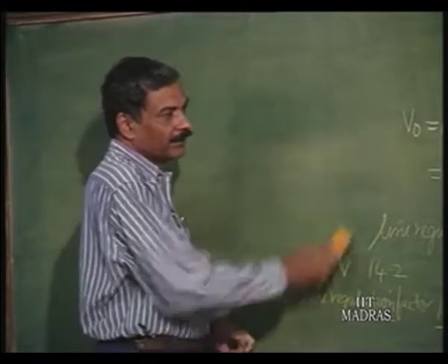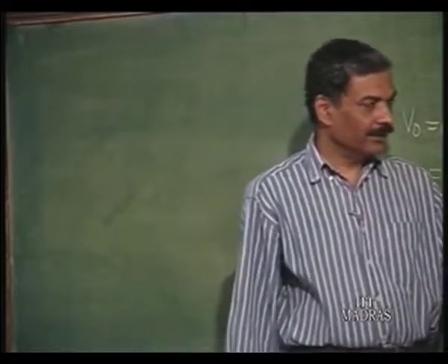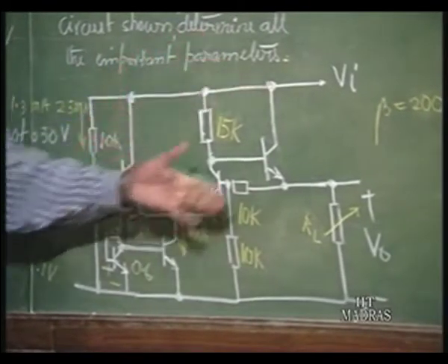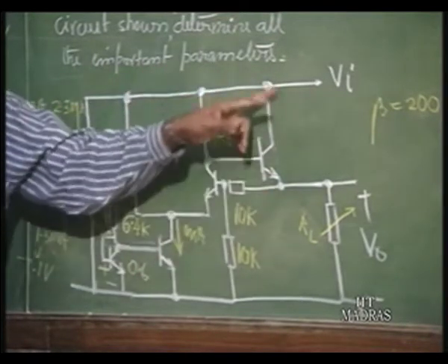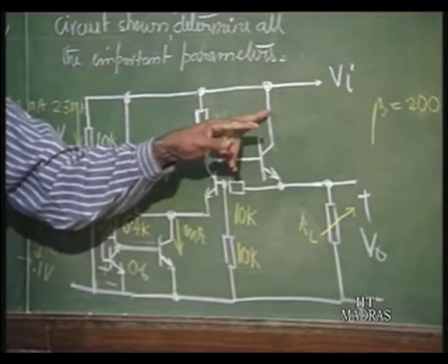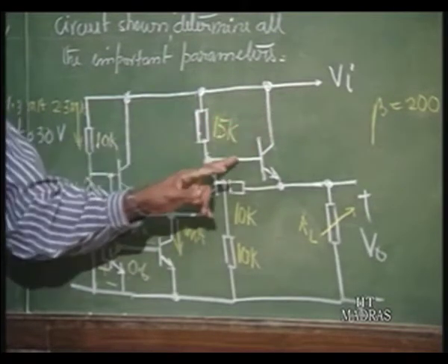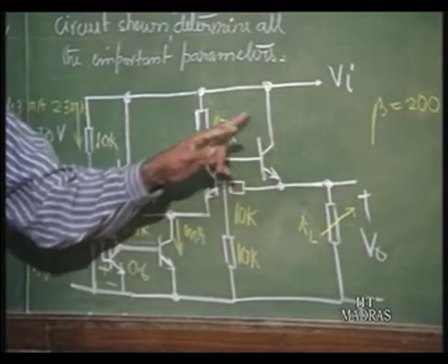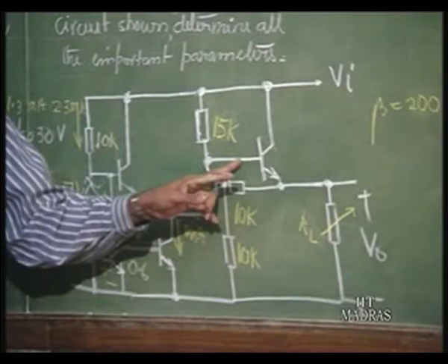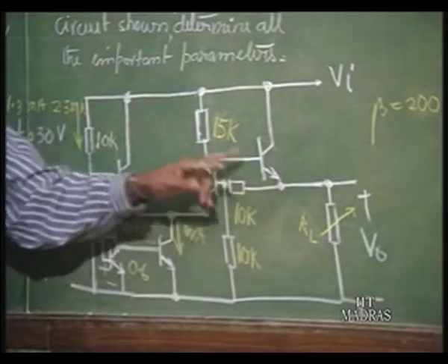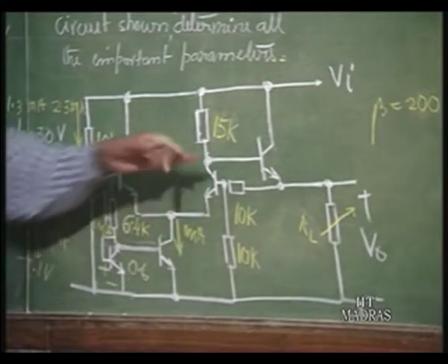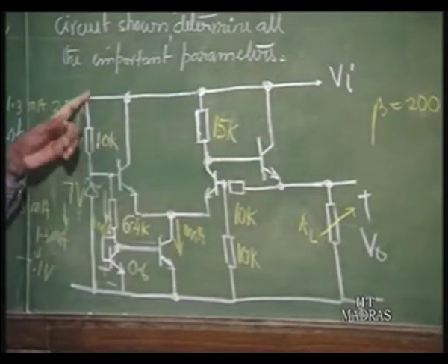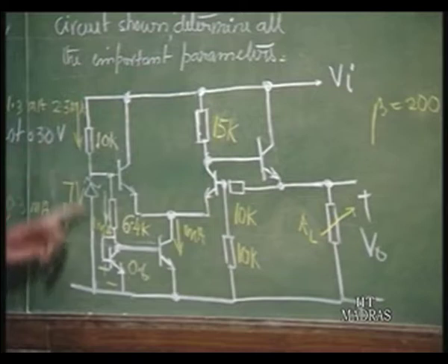So, please understand this is one way: because of line voltage variation, output voltage can vary directly. The other way is also through the link here, because this is not a truly very high impedance point, there is a reverse bias junction here, then it is connecting. If the reverse bias impedance is not too high, then there will be transmission on this side also. So, all these factors will come into picture, but the primary factor in this circuit, as I told you, is that compared to this impedance, this is very low, and therefore most of the transmission occurs through this path. Next,